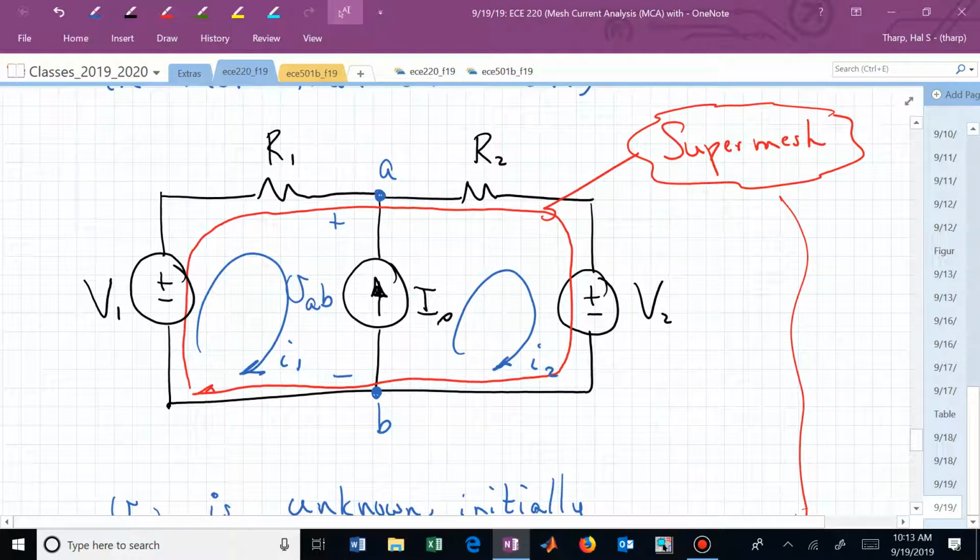This we've been doing all along, haven't we? The last 2 days. That's a long time, huh? Capital I sub s is equal to, can you define that in terms of the mesh currents? What's the net current going up? That's capital I sub s. What's that equal to in terms of your mesh currents? 6I sub 2 minus 10I1? No, it's just I sub 2 minus I sub 1.